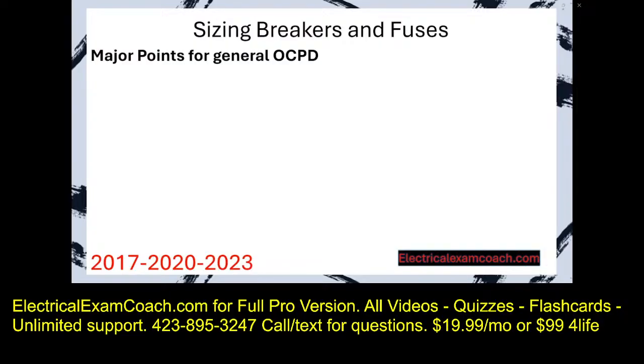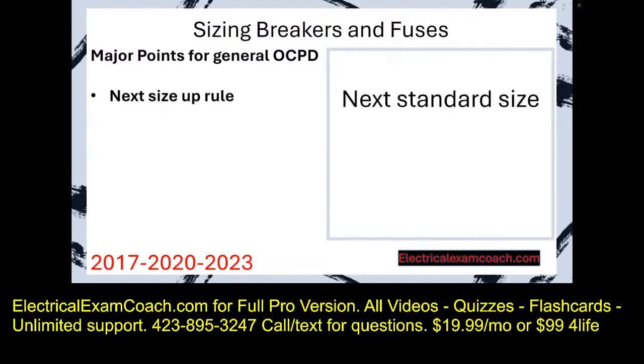But these rules that we're getting ready to learn apply blanket across the NEC unless another section tells you otherwise. The first one is the next size up rule. And that's the next standard size on that table that we just learned about. Let's imagine that we have a 59 amp known load. And for the rest of the program, I'm going to call it known load. And there's a reason that you'll learn about here in a minute.